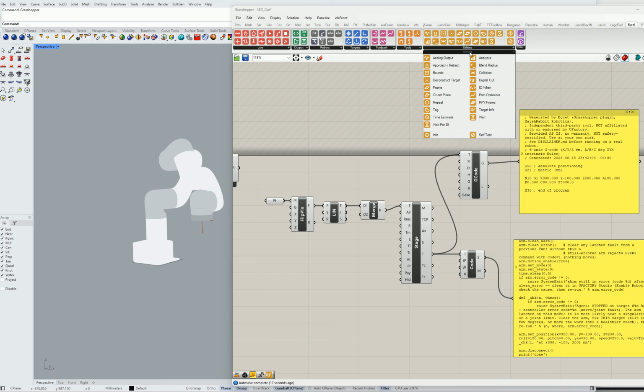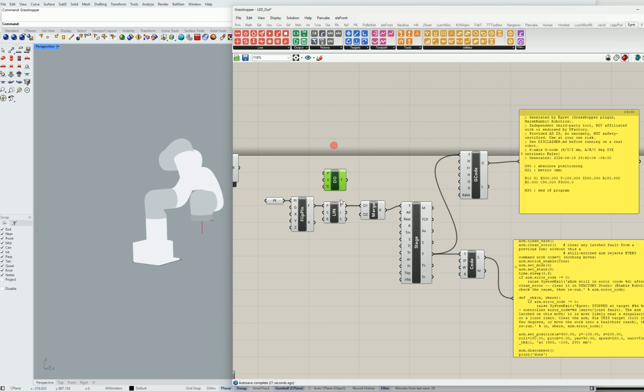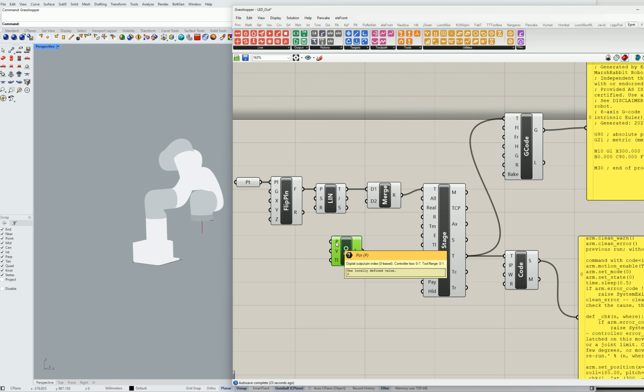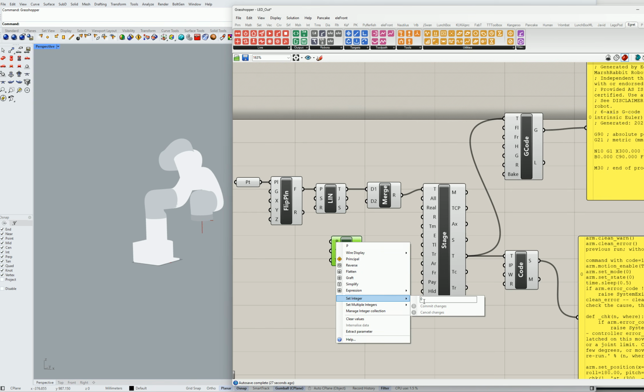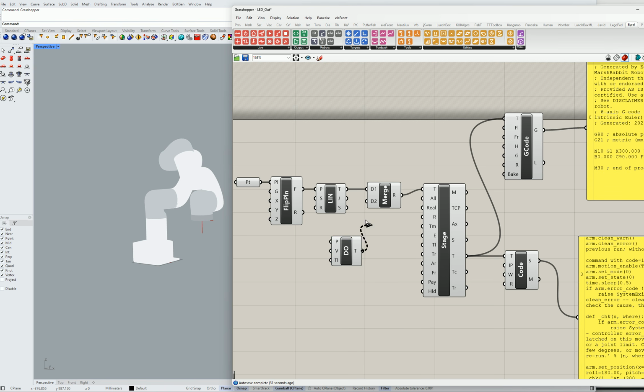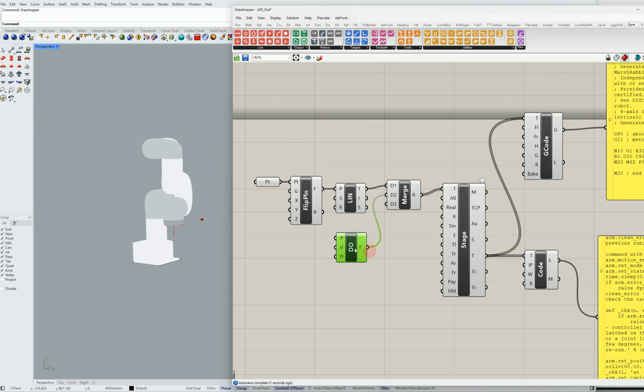We'll go to utilities, and then to digital output. You do see we have an analog output, but we're going to use digital. You can see the P stands for pin, and we can say what pin number we want to use. By default, we start at 0. And we'll drag it into the merge command there.